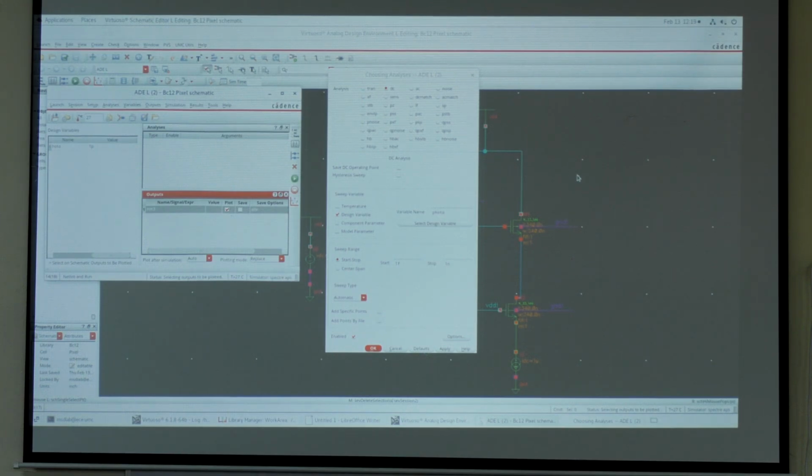See, one of the things that you have to see, you cannot get more voltage than the power supply which you are providing. So if things are going up, that's not expected, right?